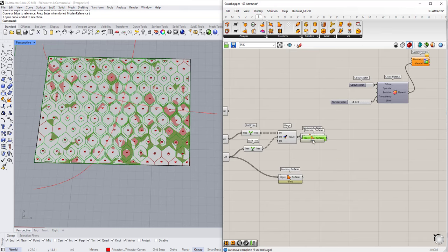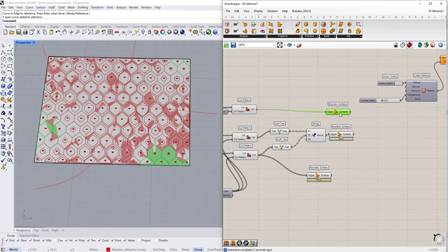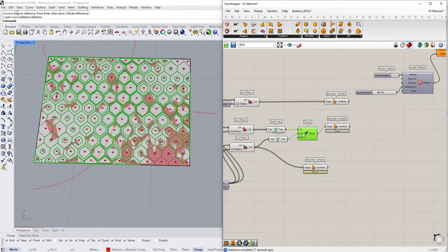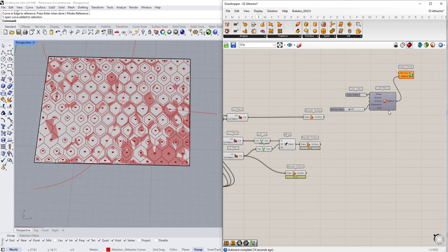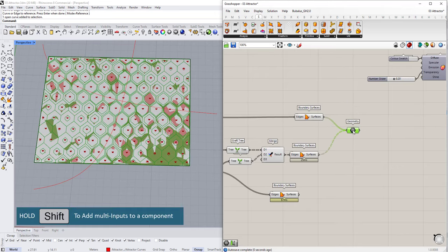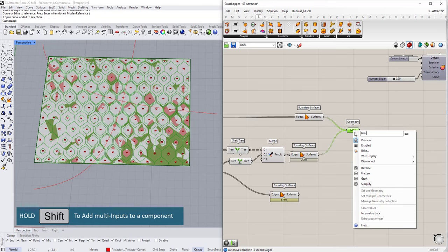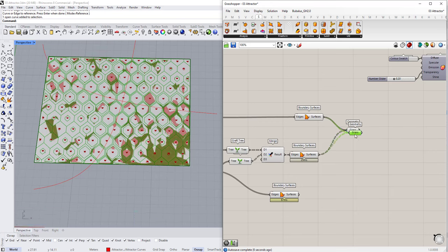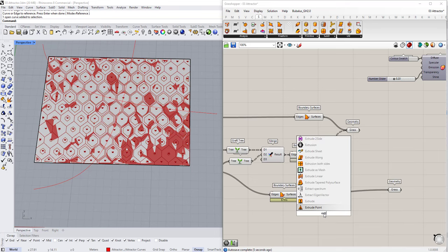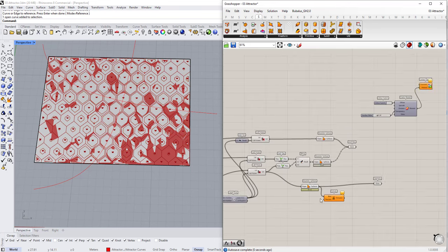And for this part, we're going to use boundary curves directly. We can, by the way, place this one here like this, but you know what, keep it like this to be more organized. Okay, add a geometry component. I'm going to add this one and this one, and let's come here and right click and name this one grass. Control C, Control V, and place this here and name it tile, but you know what, before doing so, I need to extrude in Z direction.